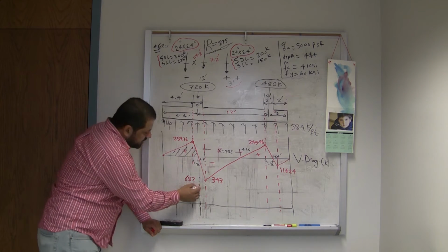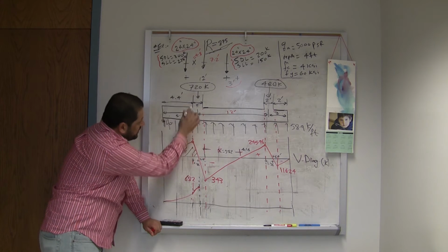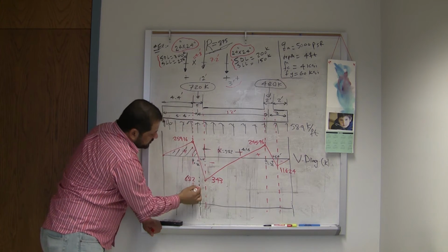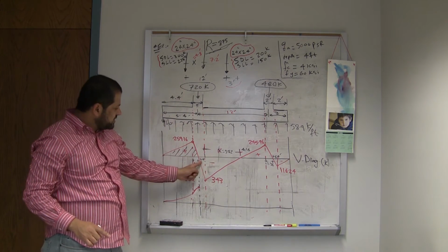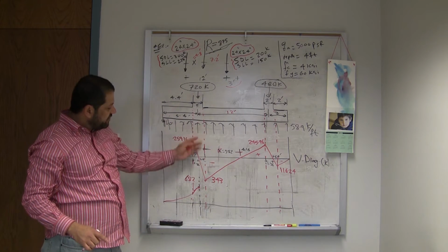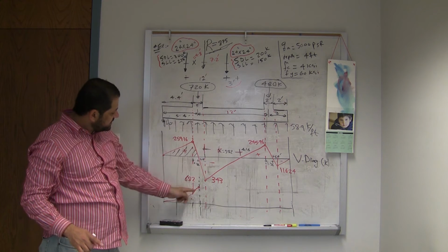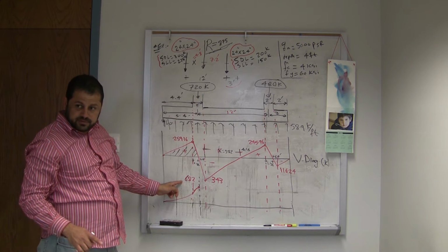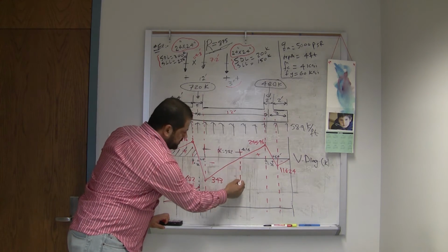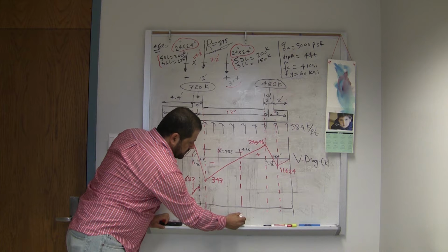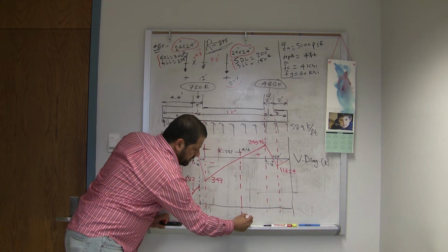Then as we go from here to here, but again, you don't worry about this small tiny piece within the column or under the column. As we go from here to here, we have this area, which is 5.82 plus 1.14, half of that times 343. That's negative. Minus 682. So that's minus 511.64. You went to 511, yes. 512.